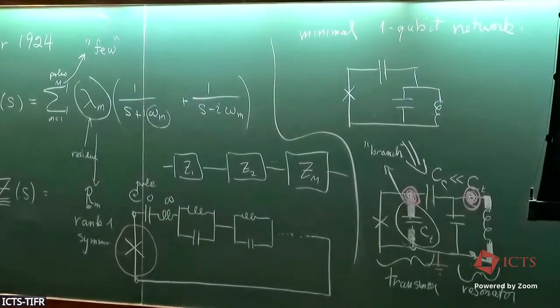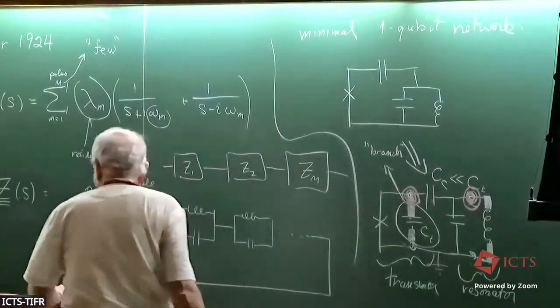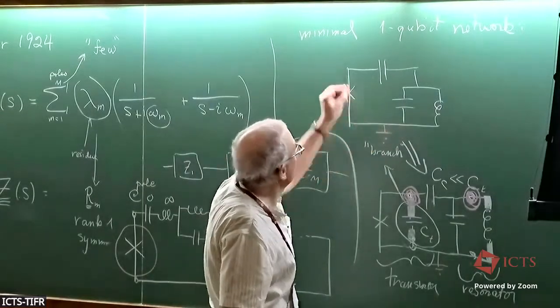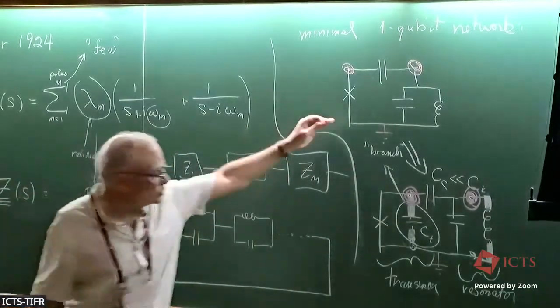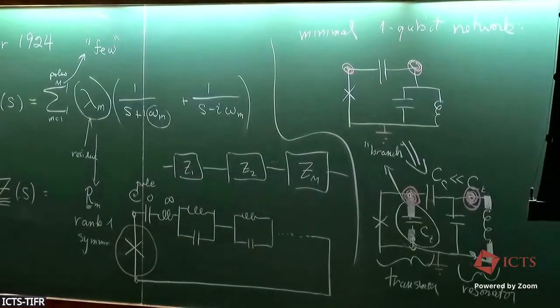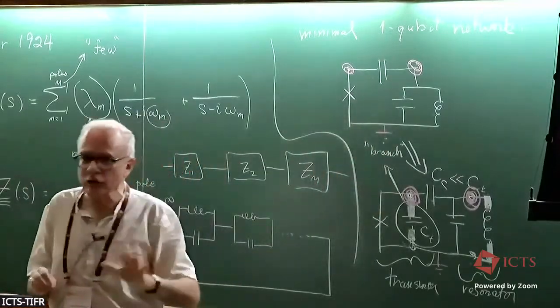There would be three phis. Well, actually, maybe the clue is that if I do this node counting, how many nodes does this have? Well, it has a ground, and it still indeed has exactly two nodes. So it's structurally equivalent to this. It has the same dimensionality of the Lagrangian. So then there are only two phis. And indeed, in both cases this is a dynamics in two dimensions, with a four-dimensional phase space. And as I said, it turns out with choices of parameters that are in fact identical.